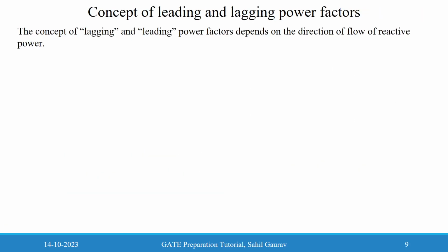Now we will see the concept of leading and lagging reactive powers. So what do you mean by lagging and leading reactive powers? That depends on the direction of flow of reactive power. For the case of load, with respect to load, if anyone is saying that power factor is leading, that means load consumes reactive power.